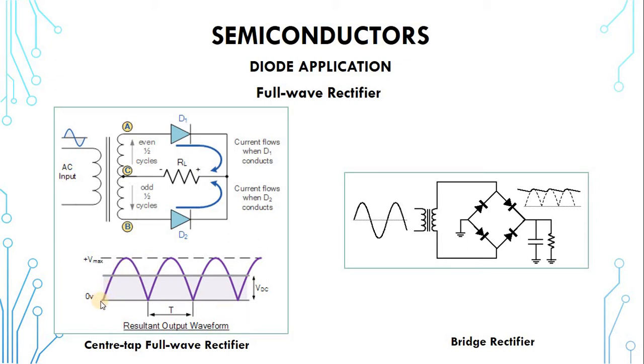So unlike the output from the rectifier, which drops to zero within a short time, this one will take quite some time before it drops to zero. So let's say when the capacitor is fully charged, it will take this full length here in order to drop to zero. So when the current rises, charges the capacitor, and begins to drop, the load takes from the capacitor, which begins to discharge until it can go to zero.